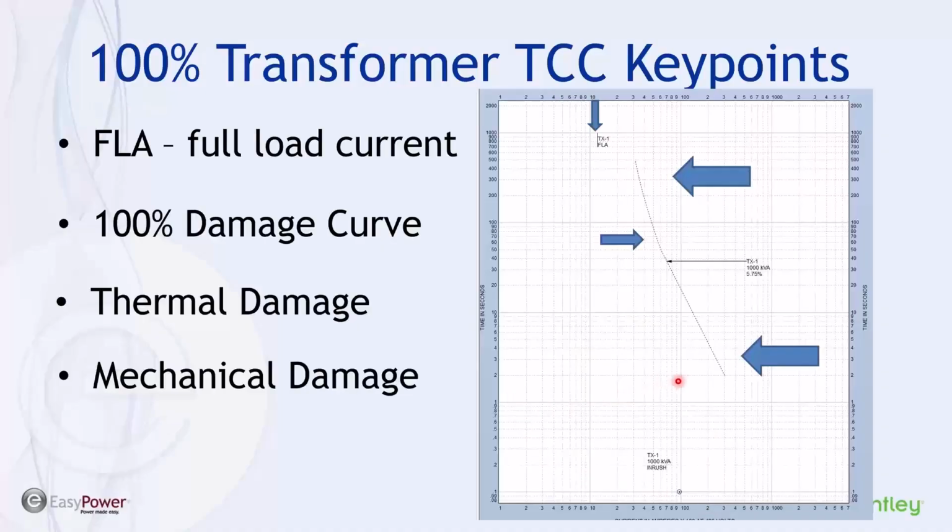So this is less than a second, and we can see potential exposure to damage if we plot, in this case, 30,000 amps for even 2 seconds as far as mechanical damage. And then there's this dot at the bottom of the plot that's described as inrush, and we will get into more description on this a little bit later in the slides.